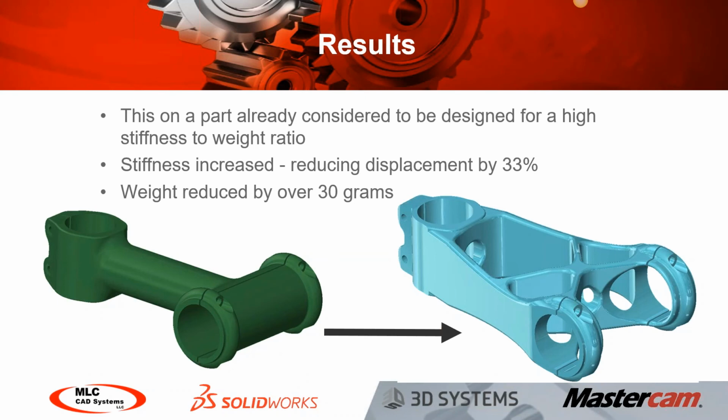I could have tried a lot of different iterations before coming up with anything close to this. The topology study came up with the design from just my maximum design space. So it's kind of helping me design that part for me. Oh, I should mention, I did that all as a single part, and then I came and split it after the fact. The topology studies do only work on single part files, not on assemblies. But anyway, I think it's really cool that it's giving me the optimum design when I just give it the maximum design space.